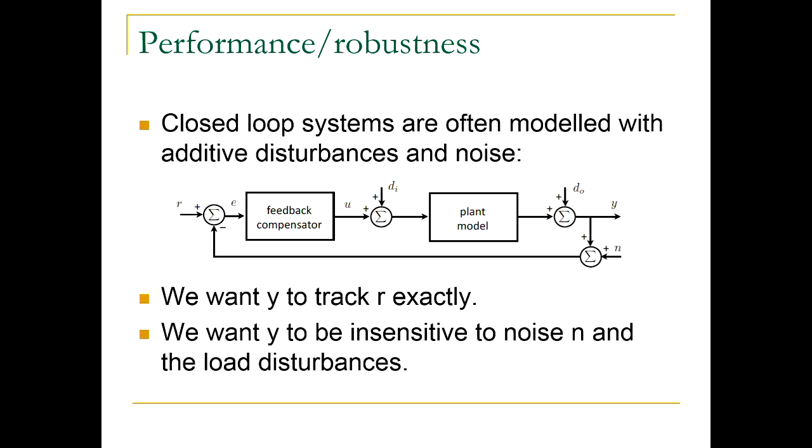So what we would like to do often, and I will now say something which you may not understand at this stage, but you can rewatch the lecture when we cover enough material. Think about this. What is this symbol here? It's a comparator, right? It basically just takes these signals and adds them up. So I can actually take this comparator and move it all the way here. What happens then is I can write here R minus N.